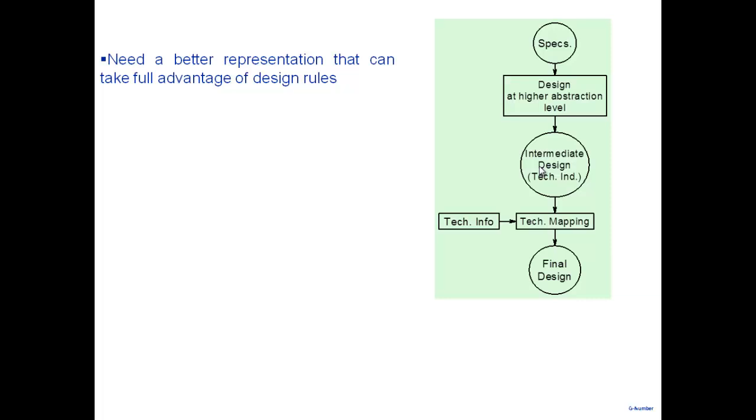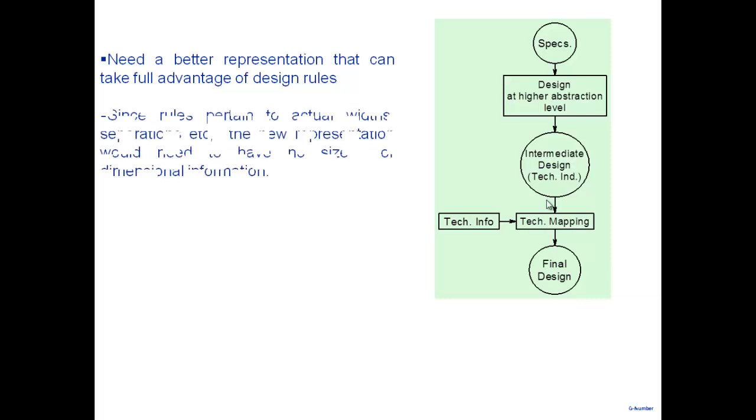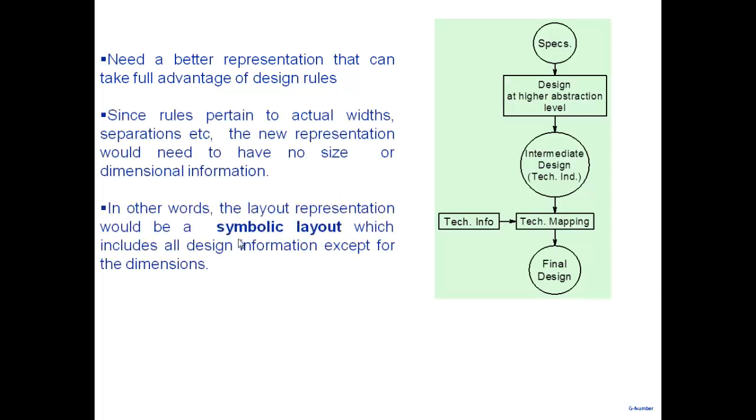Then what are we talking about? A layout without size information? Layout is all about sizes, geometrical drawings and all that. So what we are saying is that what we are looking for is a symbolic layout, a symbolic layout which doesn't have any information about the actual sizes, but still has relevant information. So what we are talking about is what we call a stick layout.